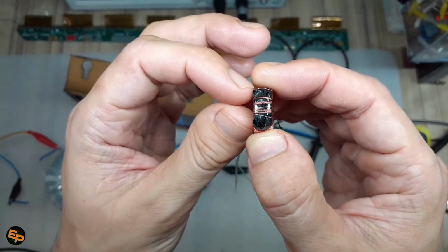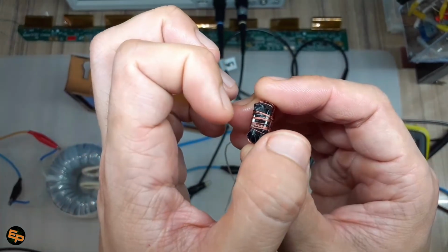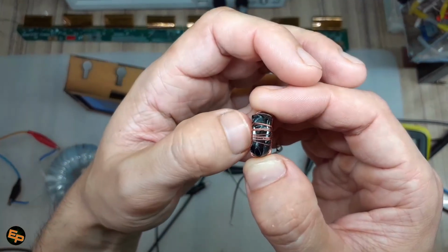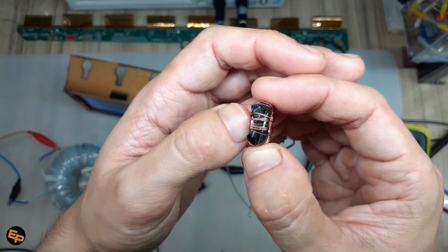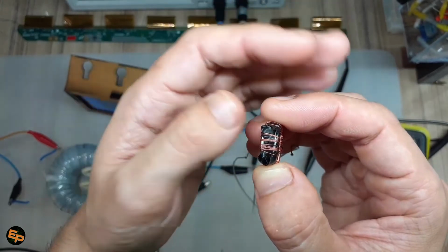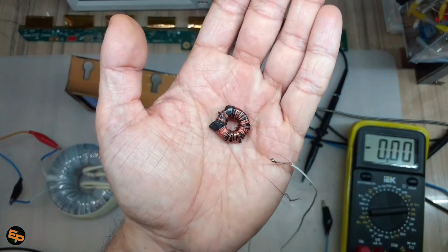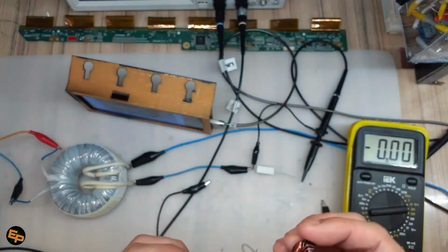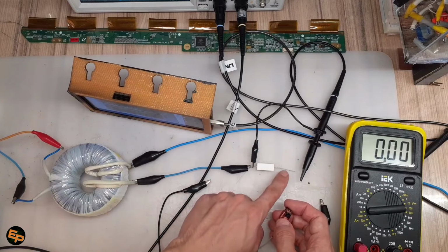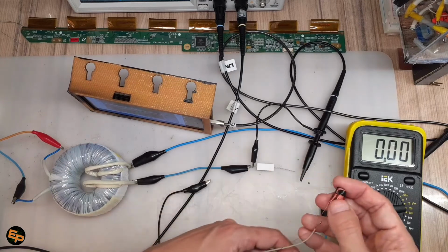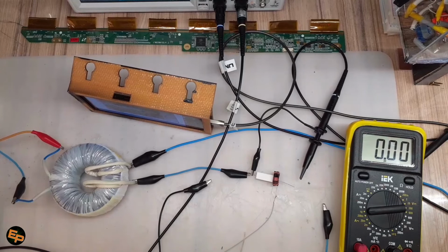And if I tilt this something like so, you can see the extreme washers in a particular corner where there is no insulation tape, but still they are insulated between them, so that's what matters. So that's what you get in the end. And in this circuit I will choose to put this shunt resistor terminal through this hole, because it's easy. And so this is how I will use my current transformer.